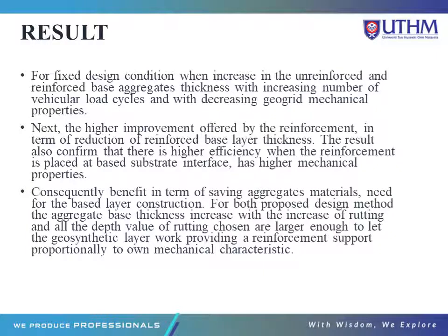Okay, next is the result. For the fixed design condition, there is an increase in the unreinforced and reinforced base aggregate thickness with increasing number of vehicular load cycles and with decreasing geogrid mechanical properties.